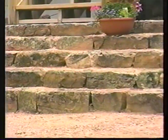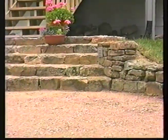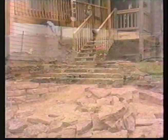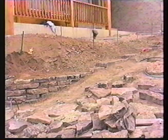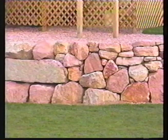Also, you'll find it easier to fit the rocks together if you minimize the angles at the top of each course. When your wall begins to run into a slope at one end, feather the wall into the slope by partially burying each course as it meets the slope. If you have joints with gaps that are otherwise unavoidable, use small rocks inserted from the back of the wall to fill the gaps.